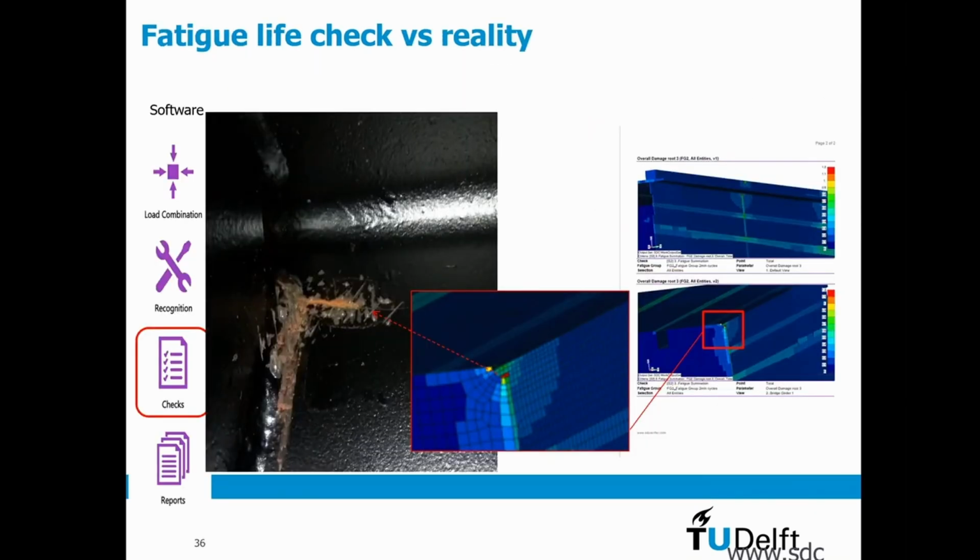I also have a couple of pictures where you show cracks found in reality, compared to the stress concentration. Be aware that sometimes the stress concentrations can be fairly small, and so you need to make a detailed model to take this into account.